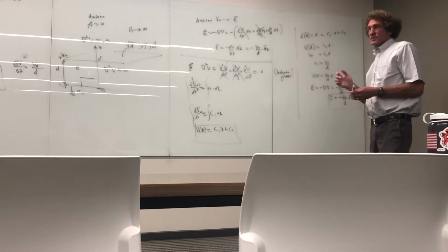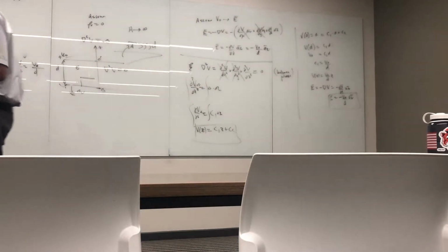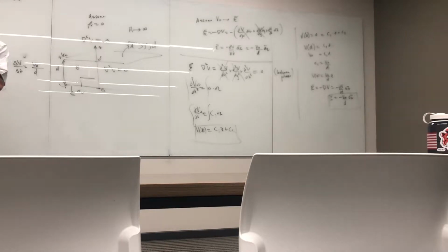Now, the real truth is, we're usually after something called capacitance. Has everybody heard of capacitance here? In your circuits courses, you always looked at it as two parallel lines with a separation distance. They gave you some equations that talked about how it can be used to determine current flow, where in steady state it was C dV/dt equal to I, and at a constant frequency you were given capacitive reactance, the ratio of voltage to current, 1 over j omega C. Those don't really tell you what capacitance means, but this is the fundamental definition.